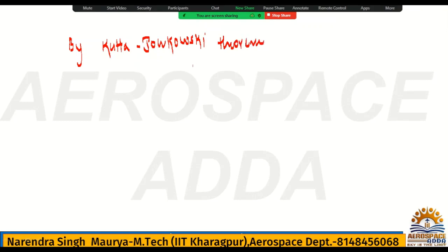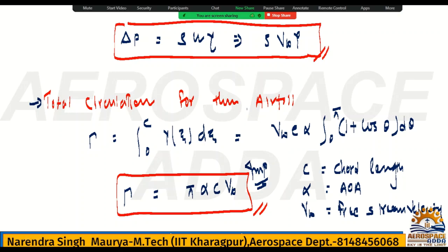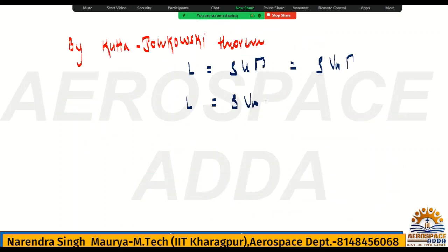It was L equal to rho U circulation. In our case, U is V infinity, so rho V infinity times circulation. Just now you have calculated the circulation. Let me write: circulation is pi alpha c V infinity.